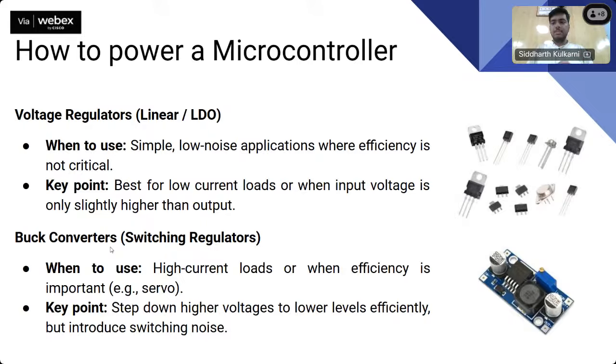That is the principal idea. If you have servo motors, or any other high load things like maybe a TFT display, screens, speakers, etc., all of those things should be driven by a buck converter, not a voltage regulator.